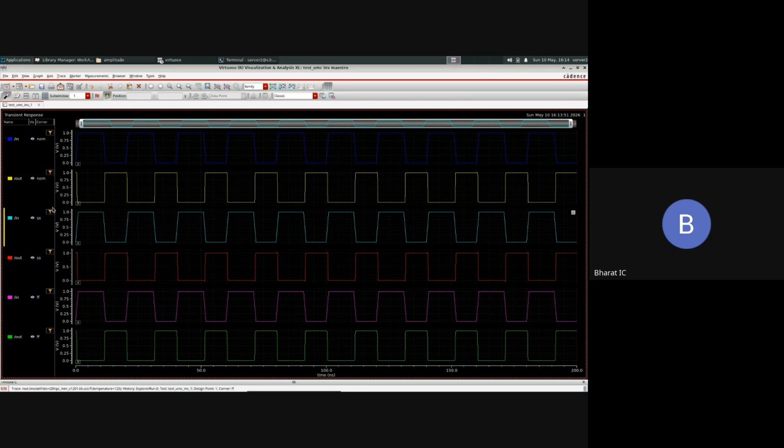So these are the 3 parameters: nominal, -40 degrees slow, and 125 degrees fast. We have simulated all these parameters to check the conditions and how our transistor functions at those temperatures. This is how we simulate each and every step. This is the whole simulation you will be taking care of. You will do Monte Carlo. Many things will come into the picture at a later stage.